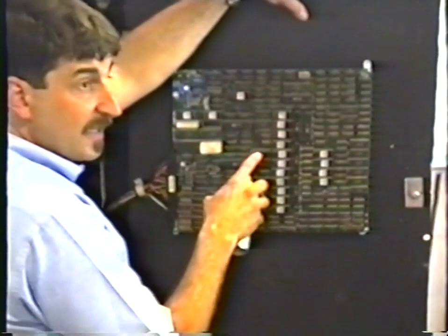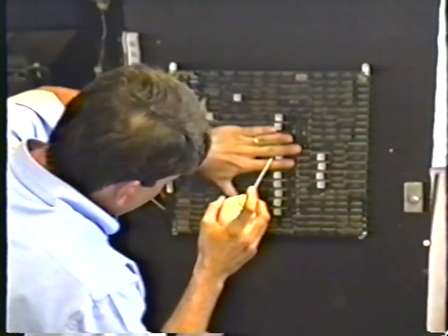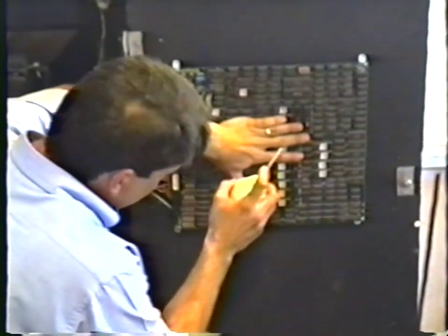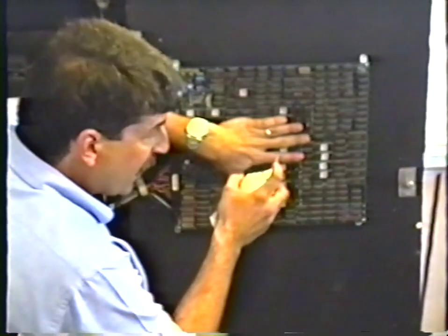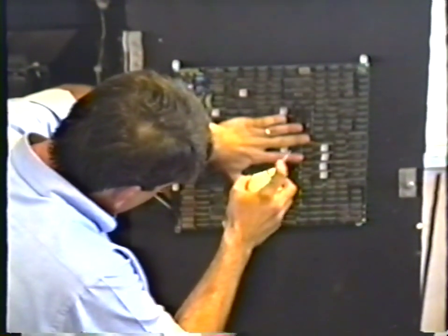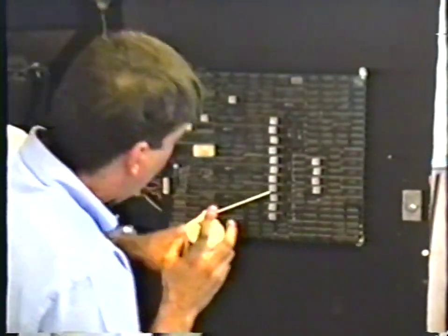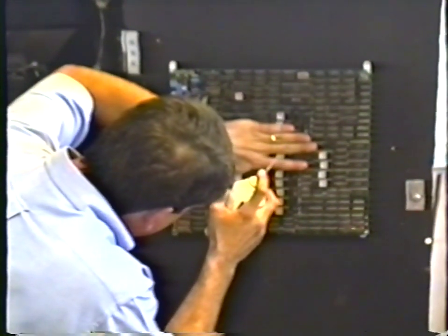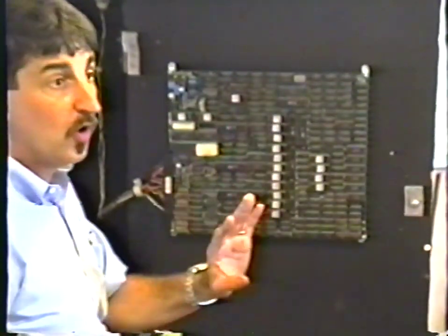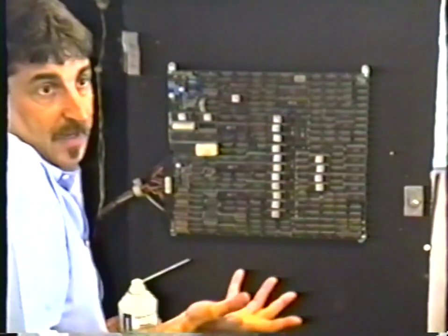Now, you may have found the right IC, you may have not found the right IC. Heat it up again with the hair dryer. Temperature cycle it many times. What I often do is I'll cover up the adjacent chips with my fingers like this, barely hit it. While you're up here, if you've got a wart or something, just go ahead and freeze that baby right off. Just hit it. Okay, problem goes away. Get the hair dryer out. Heat it up. Oh, problem occurs. Make sure that you are just hitting that one chip that you think is bad. Temperature cycle it 5 times to make sure that that's the chip, because it's really easy to overspray and hit an adjacent chip and cool that one off simultaneously.